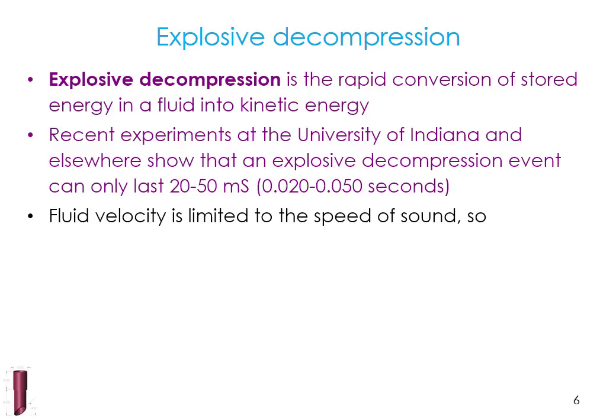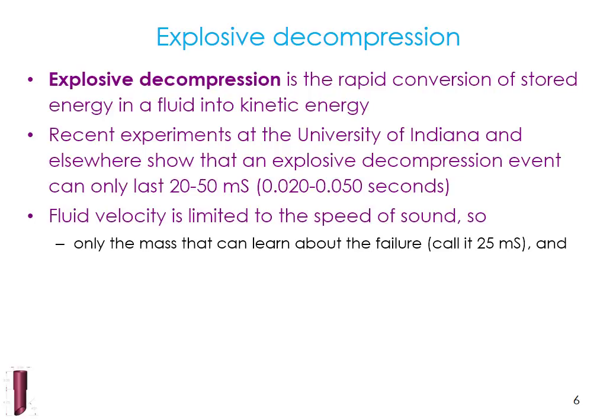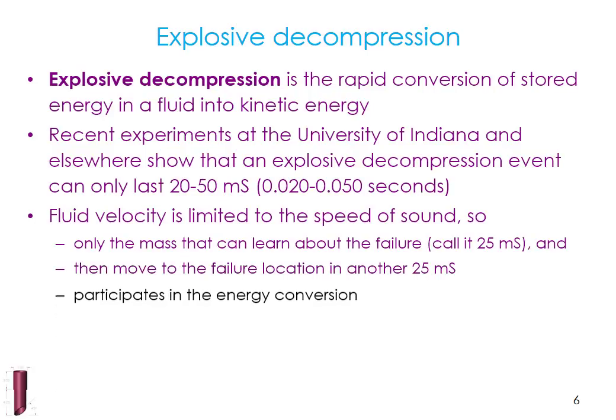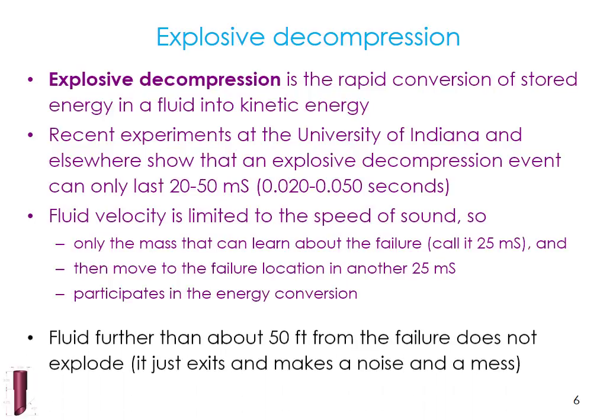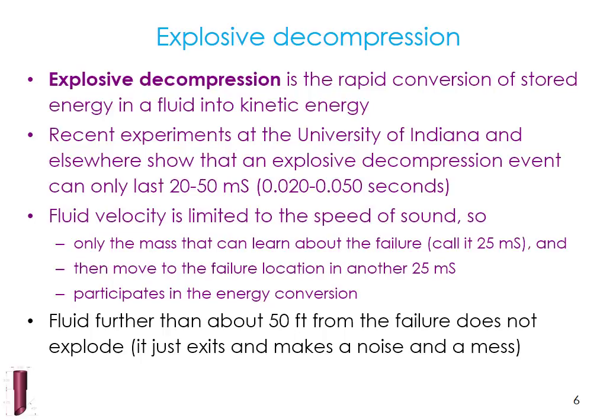The fluid velocity is limited to the speed of sound, so only the mass that can learn about the failure, call it 25 milliseconds, and then move to the failure location in another 25 milliseconds, can participate in the energy conversion. Fluid farther than about 50 feet from the failure doesn't explode. It just exits and makes a lot of noise and makes a mess. But it's not an explosion.